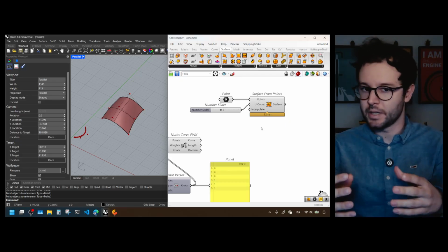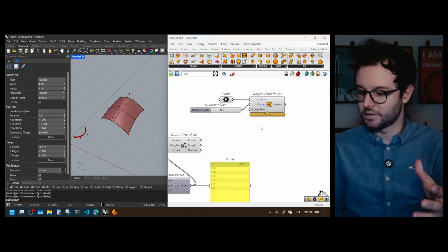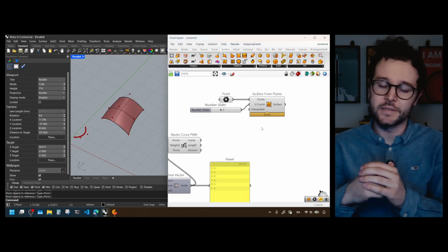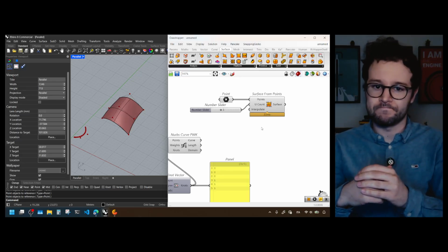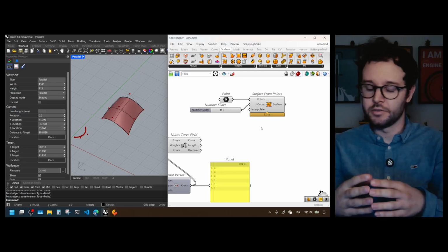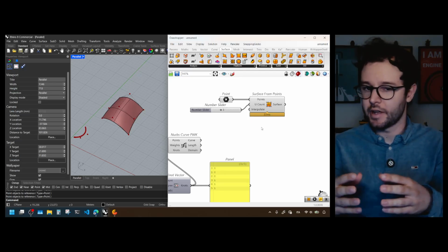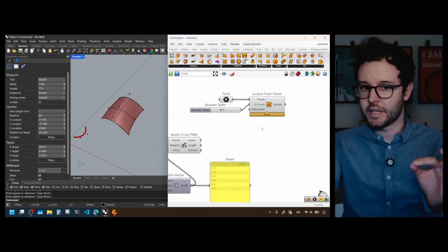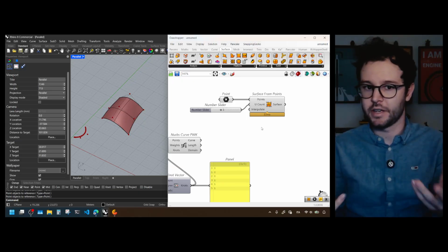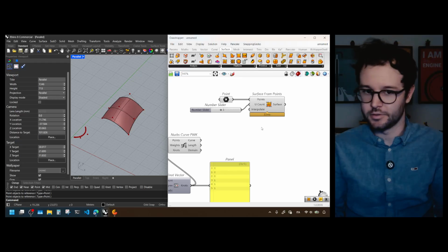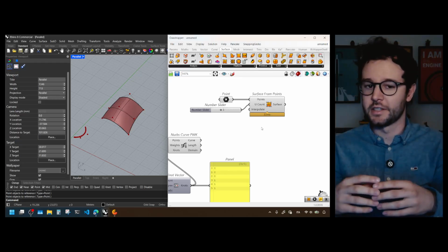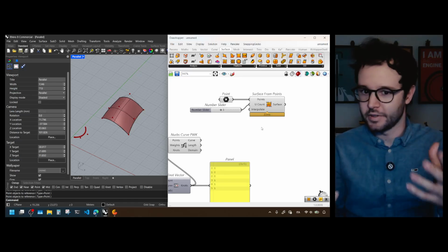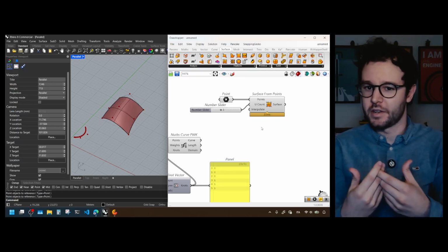And what a B-rep is, is just many NURBS surfaces all connected to each other in a clever way so that they look like a solid. And you will see that the operations we'll use are just clever ways the CAD application gives us to create these control points and connect them in the proper order so that we don't have to do it by hand, because we could draw every single solid using manually defined control points, providing the weights, providing the knots, but it would be very annoying.